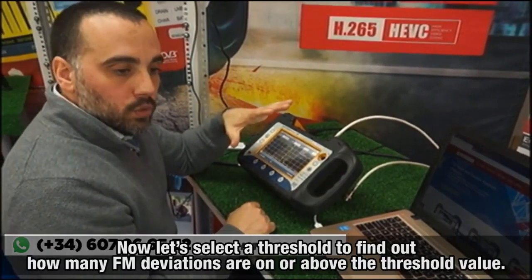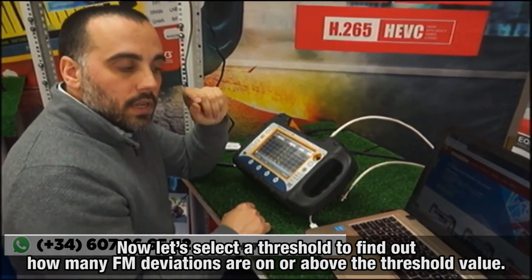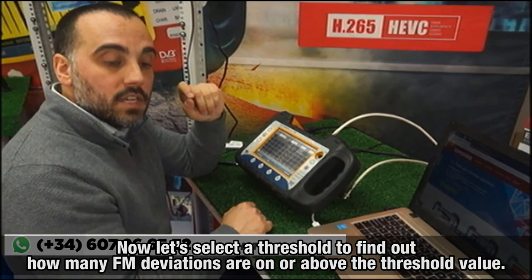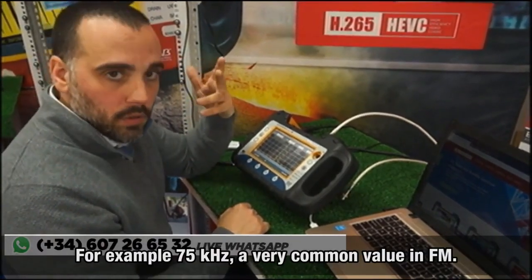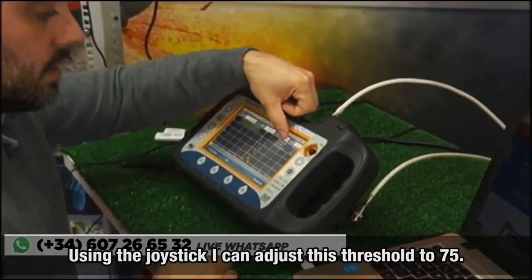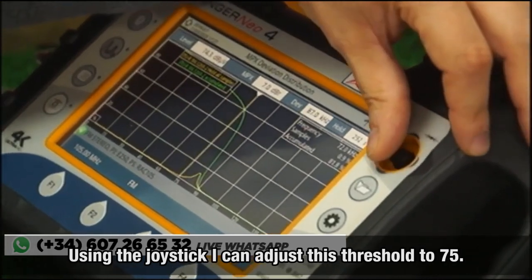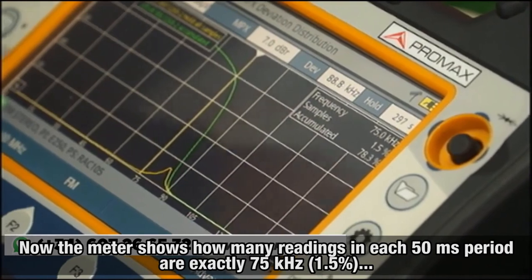So now what we should do is select a threshold. For example, let's say that we don't want our FM carrier to have an FM MPX deviation higher than 75 kilohertz, because that's a very common threshold to use in FM. So you select it here. Actually, if I move right, I could select a lower one, 71. I will select 75.